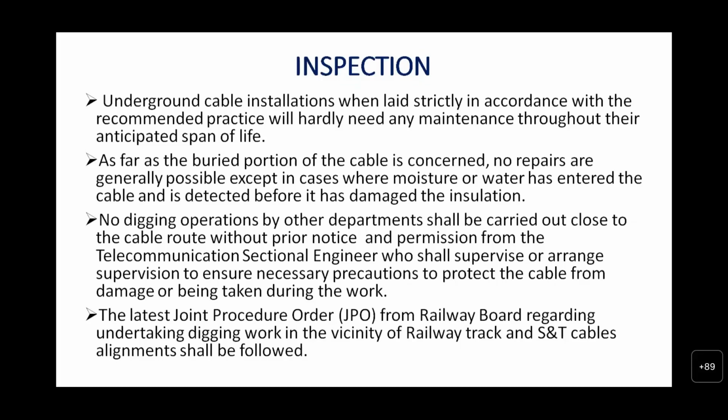No digging operation by other departments shall be carried out close to the cable route without prior notice and prior permission from the telecom sectional engineer, who shall supervise or arrange supervision to ensure necessary precautions to protect the cable from damage are being taken during the work. The latest joint procedures JPO from Railway Board regarding underground digging works in the vicinity of the railway track and SNT cables alignment shall be followed scrupulously.